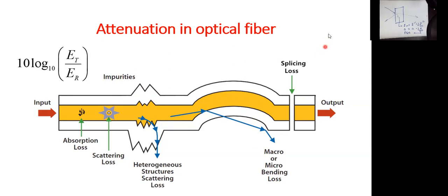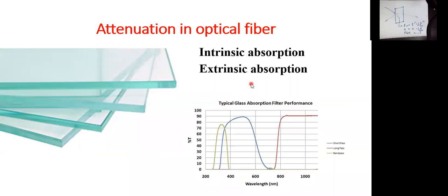And what's called also splitting. This splitting occurs whenever you are connecting this optical fiber with another optical fiber or with your terminated device, and sometimes there is some air gap in between. This air gap, of course, will cause some losses because light will escape outside the optical fiber. So these are some of the reasons that strongly contribute to the attenuation and justify why we may have an attenuation effect in the optical fiber. As I mentioned, glass, in some frequencies, has an absorption effect, so that we have absorption.